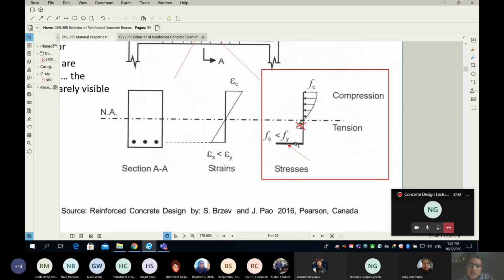Now, what happened, guys, is you can see here. I'm going to talk right now about one moment when the entire beam fails. As I said before, if your beam is plain concrete without any reinforcement, then we know exactly when the beam will fail, which is when the stress at the bottom fibers of the beam is equal to f sub r, so that's cracking, and then the beam will collapse. Now, when we add some rebar, the beam will not collapse. However, it will hold more loads.